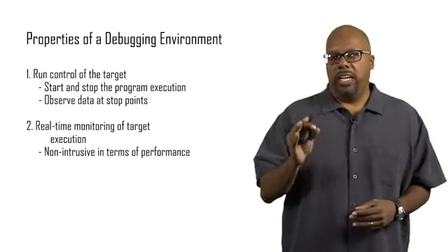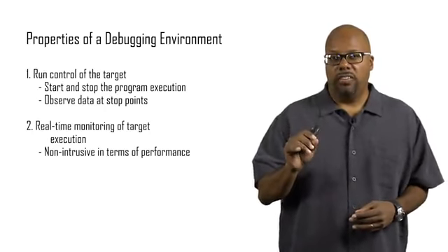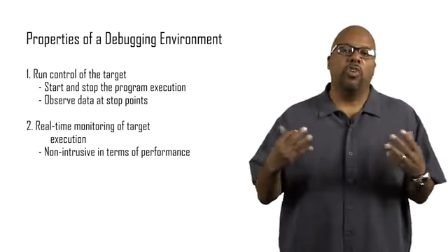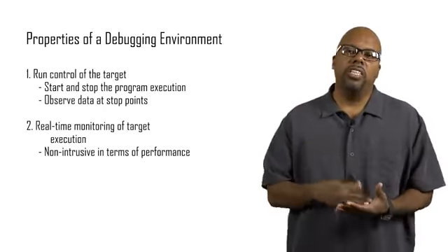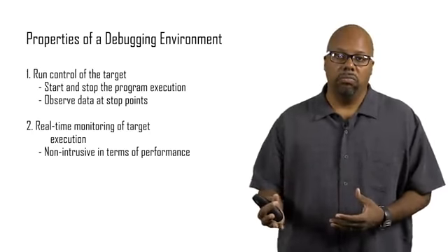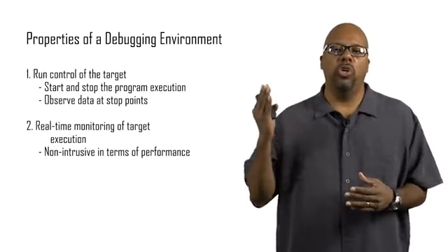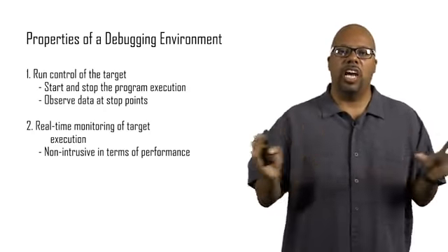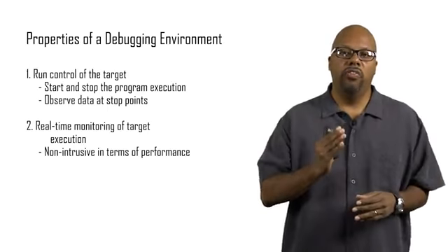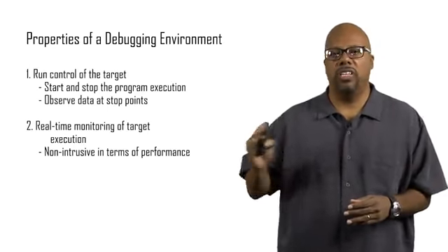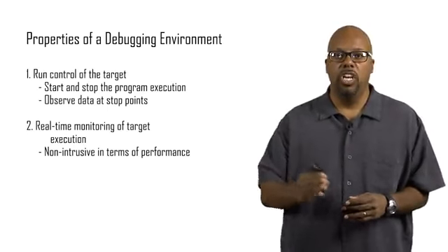Now, in a lot of IoT devices, the timing is very important to the correct operation of the system. If you don't get the timing right, it doesn't work. So real-time monitoring is what you would like. Real-time is where you don't set a breakpoint and stop the execution. You view data about the execution in real time, as it is executing.